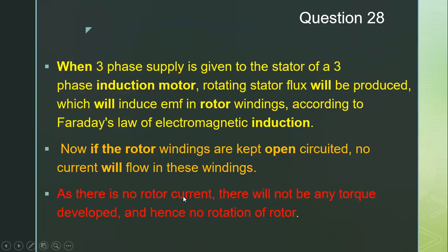We need a closed circuit in the rotor, then only it produces torque. That is the basic working principle of a three-phase induction motor. You know that the rotor should be short circuited.